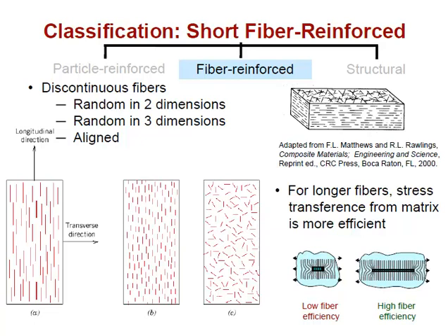As you move into the fiber, that stress gets transferred with distance from the matrix into the fiber along the ends. So right at the very end of the fiber, it's not really carrying any load. Stress transfers to the fiber by fiber length via its circumference. And so it takes a long fiber, fairly long, to transfer stress from the matrix.